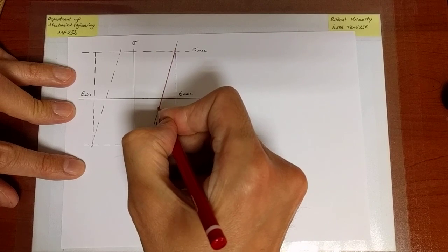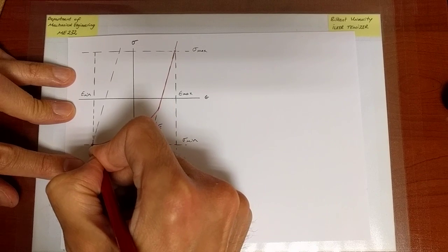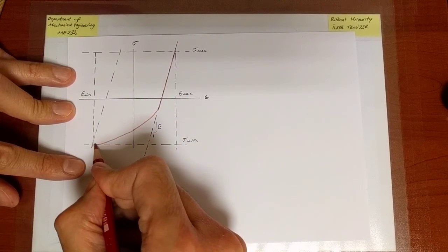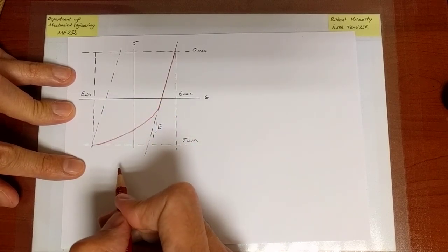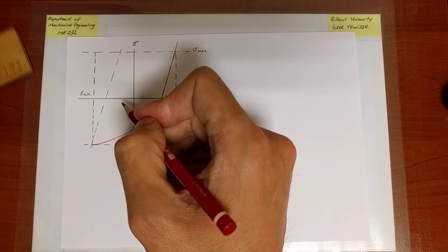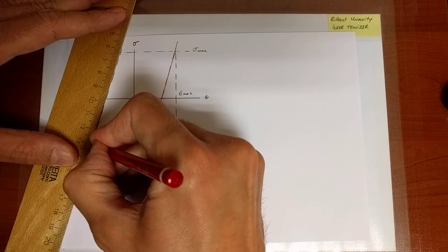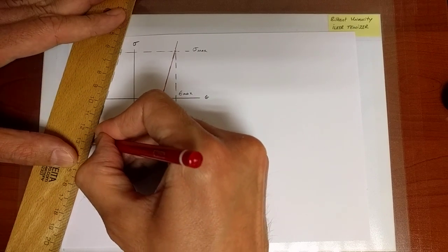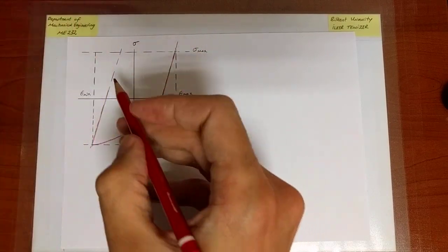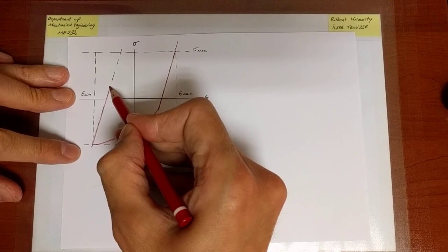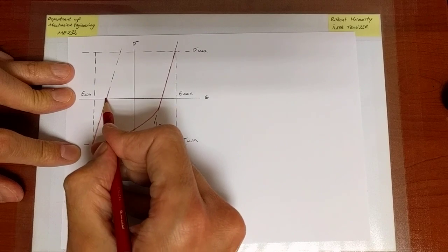So let's depict it with such a line. Okay. And then we reach the minimum strain at which we observe the minimum stress, and then we start reloading. And unloading is again elastic, and therefore on a line, and we unload until it turns out there is again some deviation from this line at some point during reloading. So when we hit zero stress, it's completely unloaded.